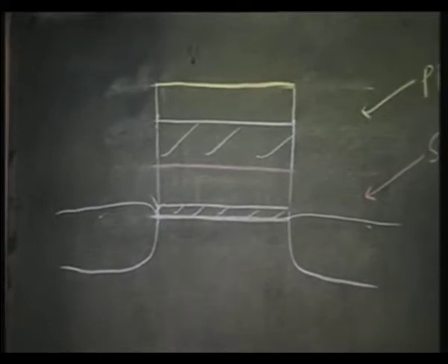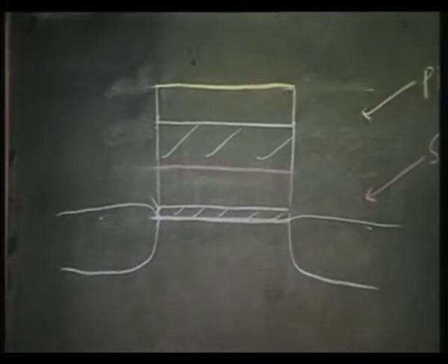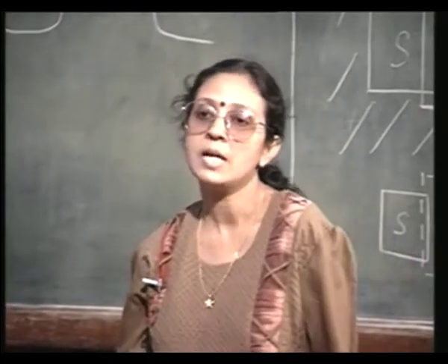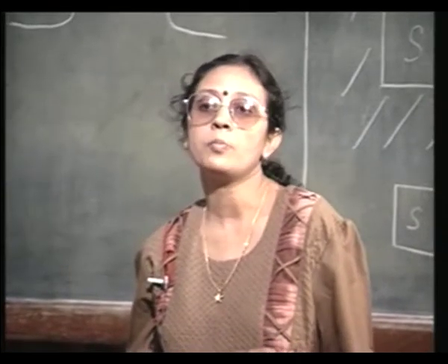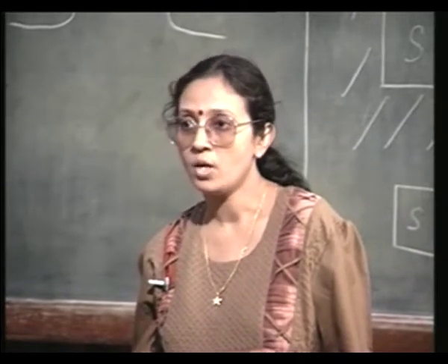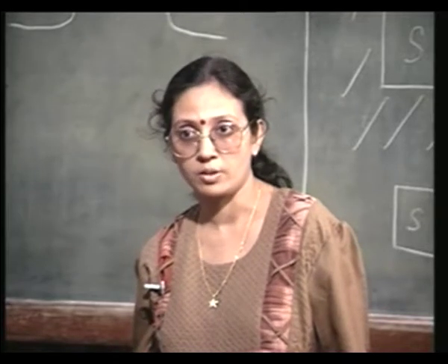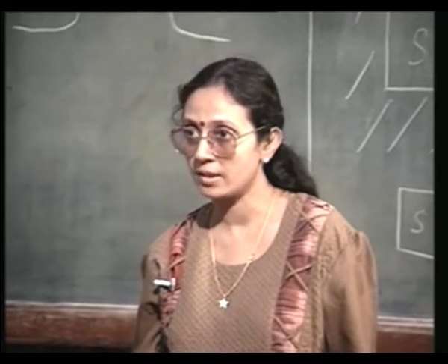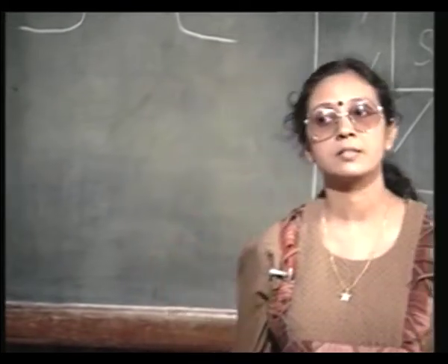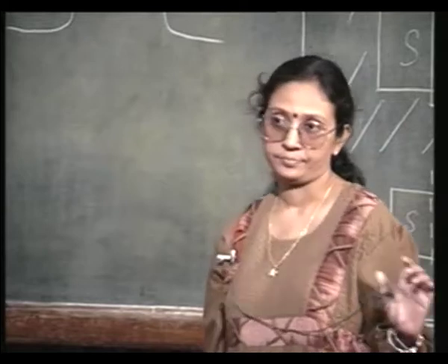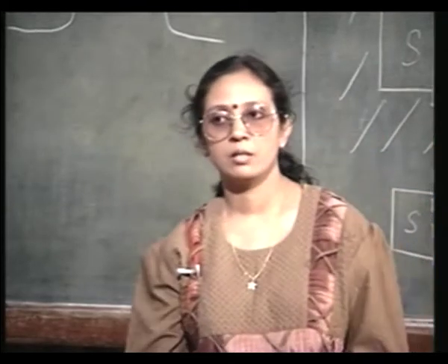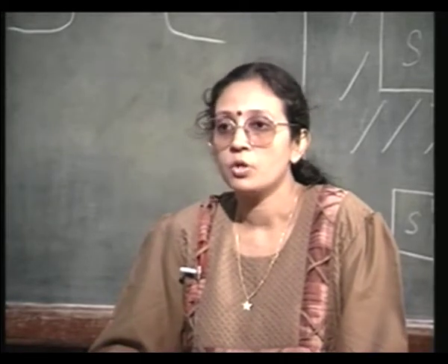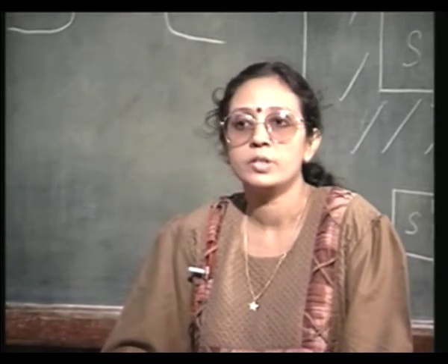Right. So, this is LOCOS, fully recessed LOCOS. Fully recessed, what does it mean? That is, after the oxidation, the top oxide surface coincides with the surface of the semiconductor. It does not protrude anywhere above the surface. You have a perfectly planar surface. But every technology will have its drawback. LOCOS is also not entirely free of this drawback.